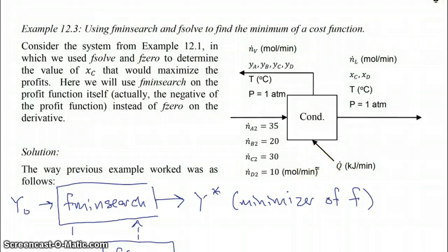But even if I condense nothing, I also have a maximum value of xc that I'm going to run into, which was about 0.955 or 0.96 or something like that, which was the composition of the first droplet to condense at the dew point temperature, remember. So the physicality of the system puts very strict limits on what values of xc might obtain in my system.